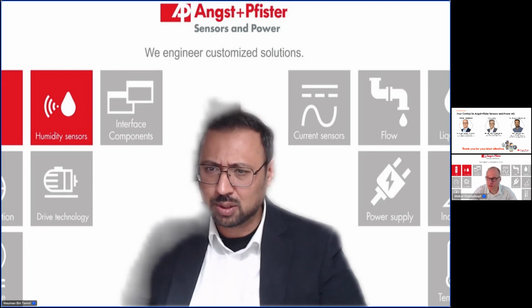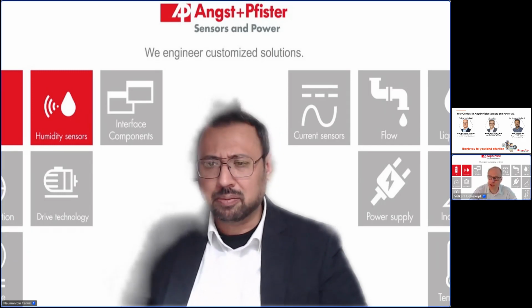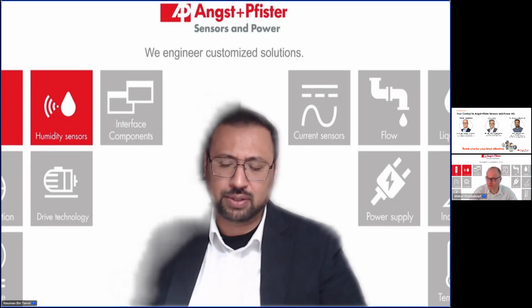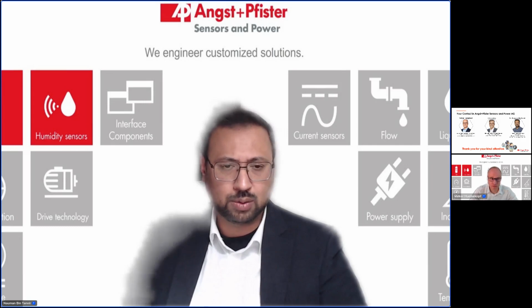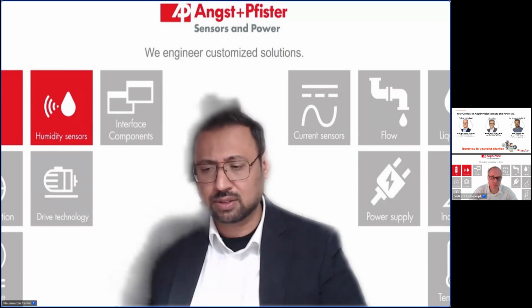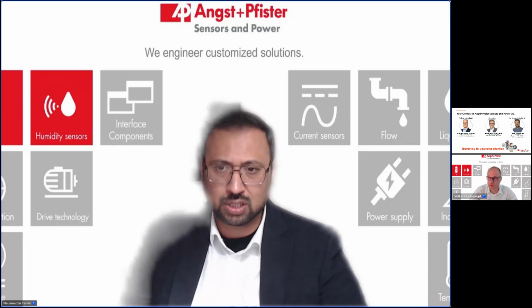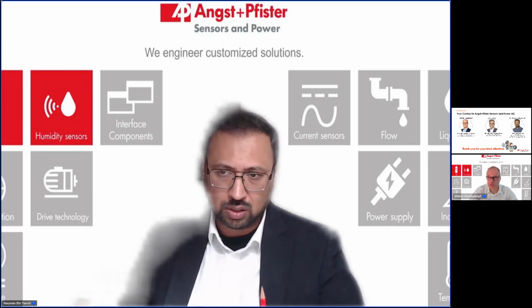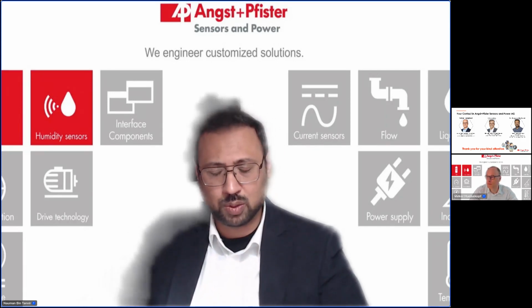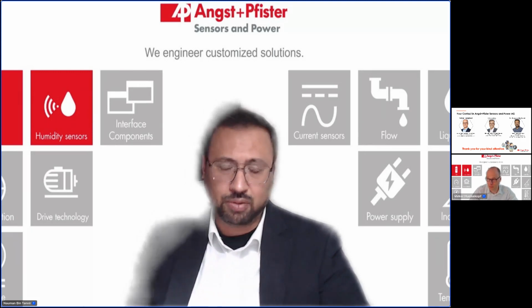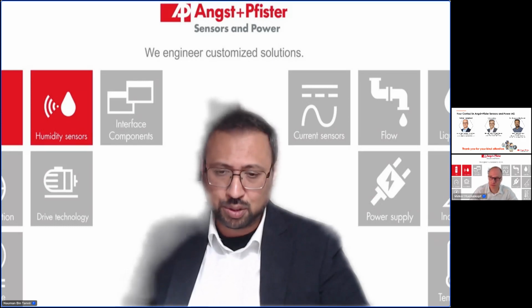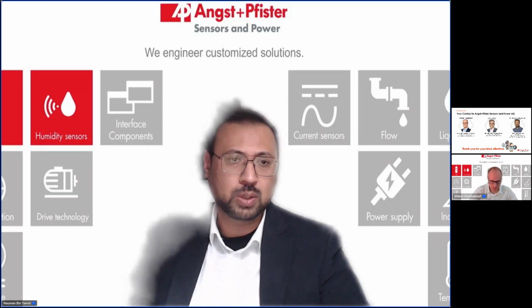What was the first question, Volker? Which of the technologies presented is the best for low ppm reading? Yes. As was also mentioned in the webinar, the potentiometric zirconia is one of the very well-known technologies that has been used for many years for the detection of oxygen at ppm level. The reason behind it is that this working principle, or the combination of the working principle, works in such a way that the ppm measurement can be performed very accurately. Another thing which I would like to add in our potentiometric zirconia oxygen sensor is the two different measurement ranges.